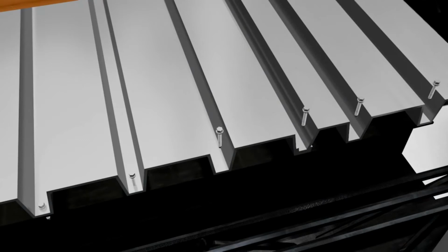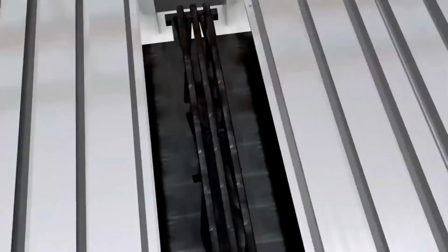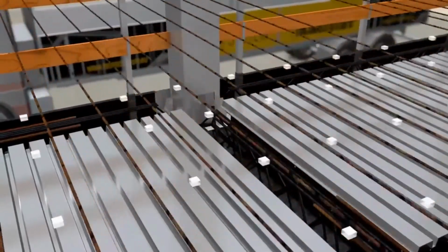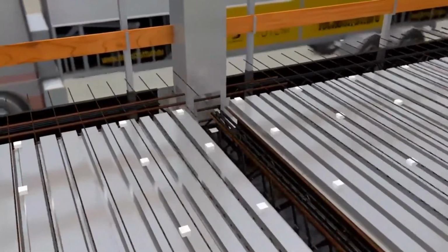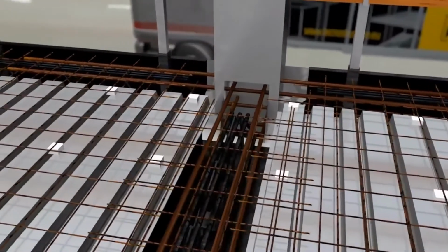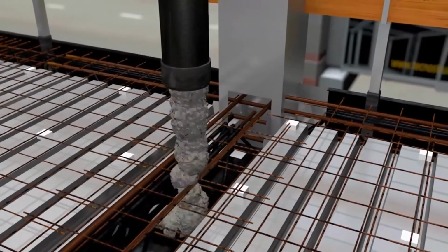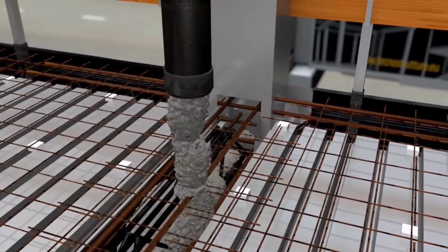In composite members, the force applied to this connection is mainly, but not entirely, shear on the longitudinal interface between the materials. As with bolted and welded joints, the connection is a region of severe and complex stress that defies accurate analysis, and so methods of connection have been developed empirically and verified by tests.